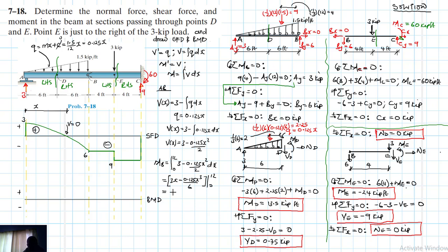For sure, we are getting exactly 0. So let's plot that quickly. Like we said, this is a quadratic. And when we look at our shear diagram, let's call this point here where we have the maximum, we call it point F.